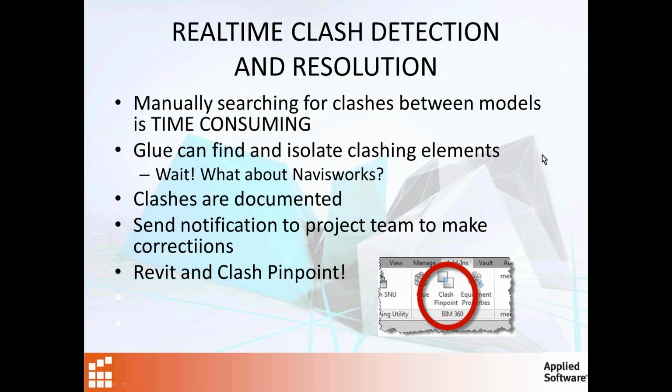And then everybody asks the question, well, what about Navisworks? Is this a replacement for Navisworks? No, it's not. With Navisworks I have many other abilities, such as the sequencing that I can do with Navisworks. I can't do that with Glue, but with Glue I can do the clash detection. It's very easy. Can I still use Navis? Sure, you can do it, but in design mode for architects and engineers, Glue is a much better option for you. So we're not replacing Navisworks here. It's another program in addition to Navisworks.